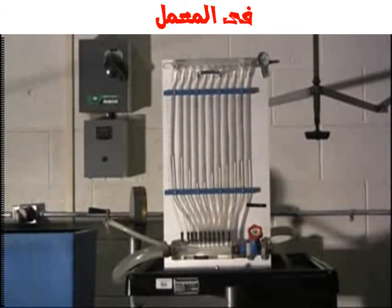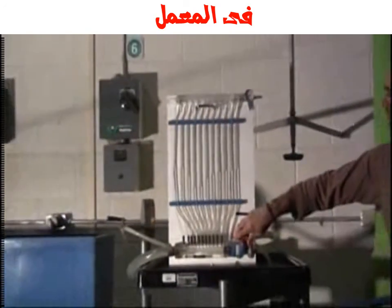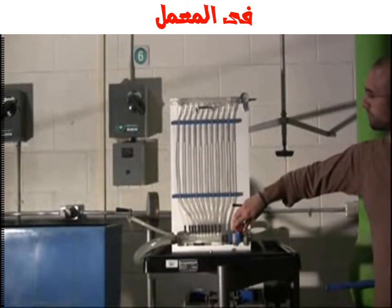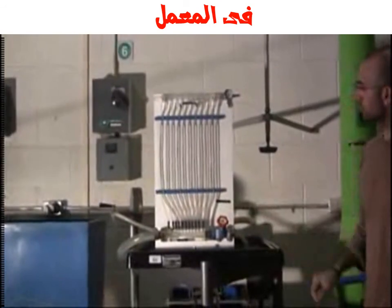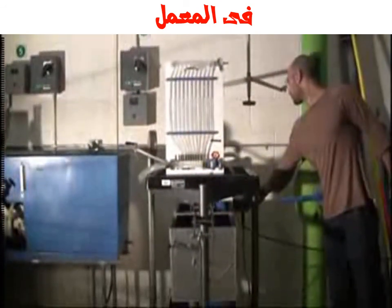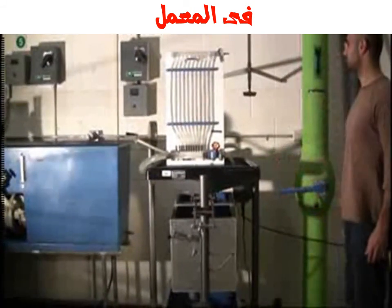The following procedures is to shut down the apparatus. Now turn off the flow completely by turning the red valve clockwise. Now shut down the pump and unplug the power cord from the wall and stow it in a safe place.